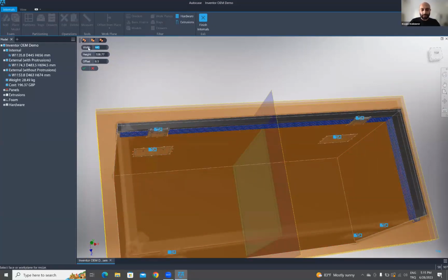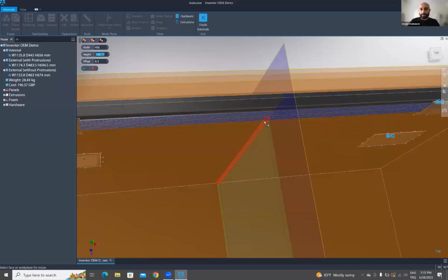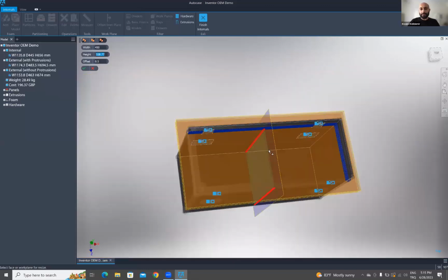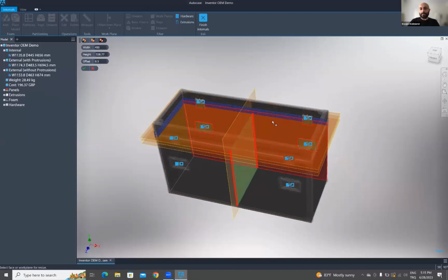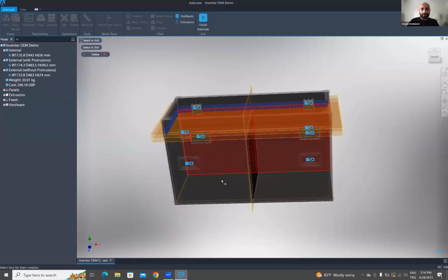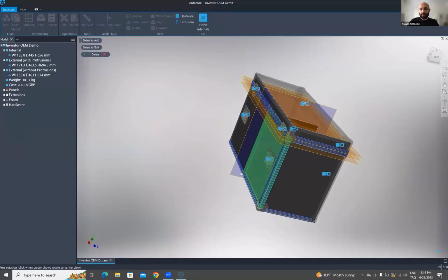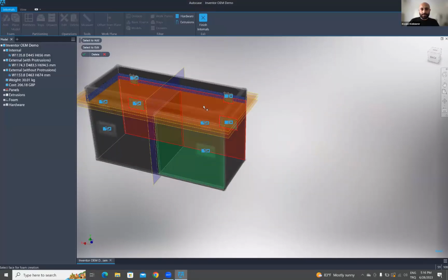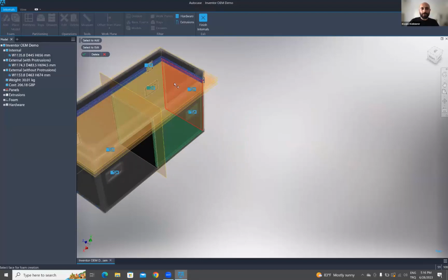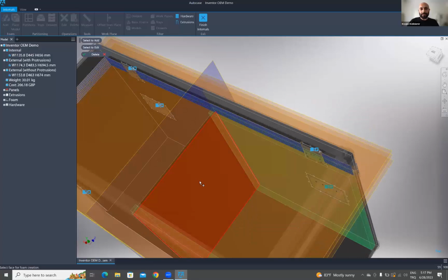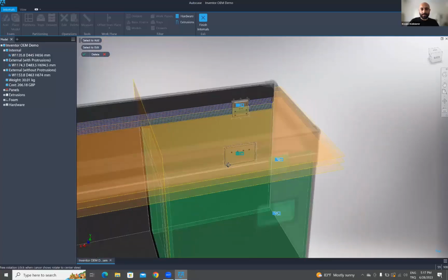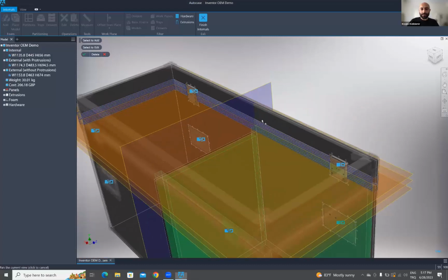But if you increase the width of the panel divider, it comes with the rebate, and it's highlighted as red. This means when I add this panel, the rebate channel will be added on the back face and the front face panel, and that's all. So when you select the faces, it fits a proper form block as a preview on the selected faces. So it's so intuitive, sorry. So it senses the limits of the face and places the correct form block with the correct dimensions.